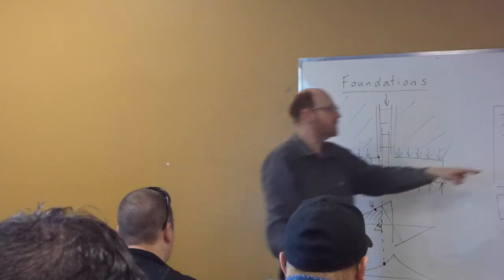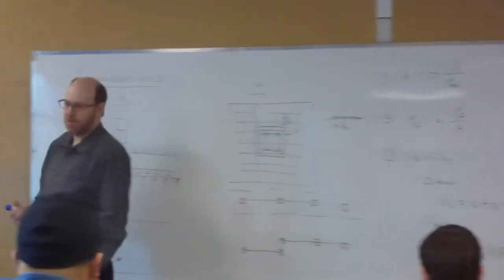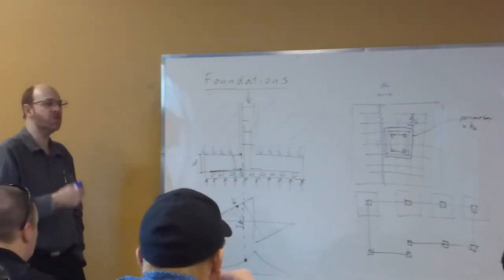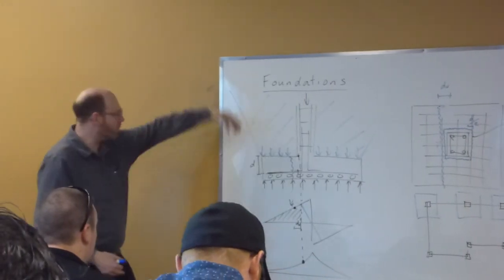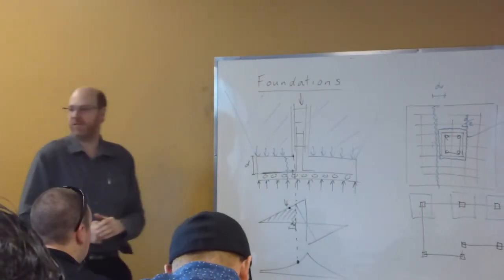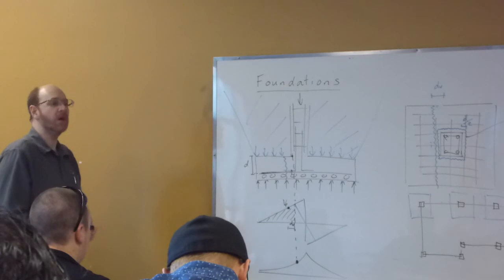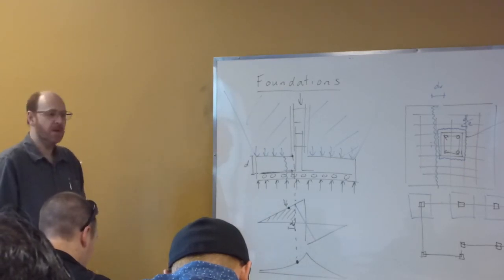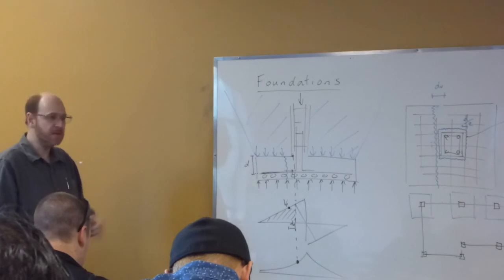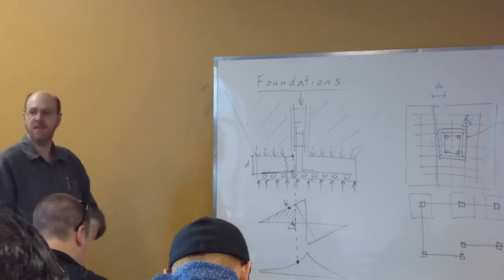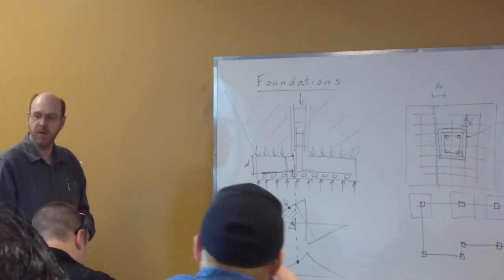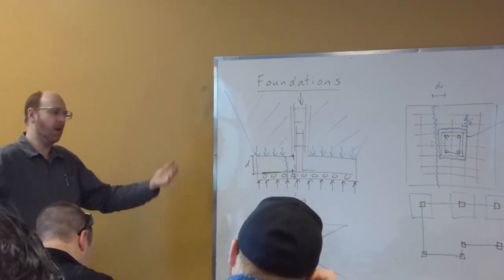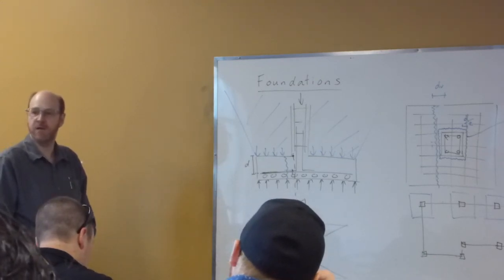So when we start at this point here with this Q allowable, technically what we should be looking at is net soil pressure. So subtracting off of that any soil pressure from the footing that you have placed above it. So the deeper that is, the more of an issue that's going to be. That ends up making a bigger and bigger footing, which is not necessarily a bad thing, because if you're having to put it deep in order to mobilize that soil pressure in an uplift scenario, putting a bigger footing means you're mobilizing more soil, so that actually works to your advantage.